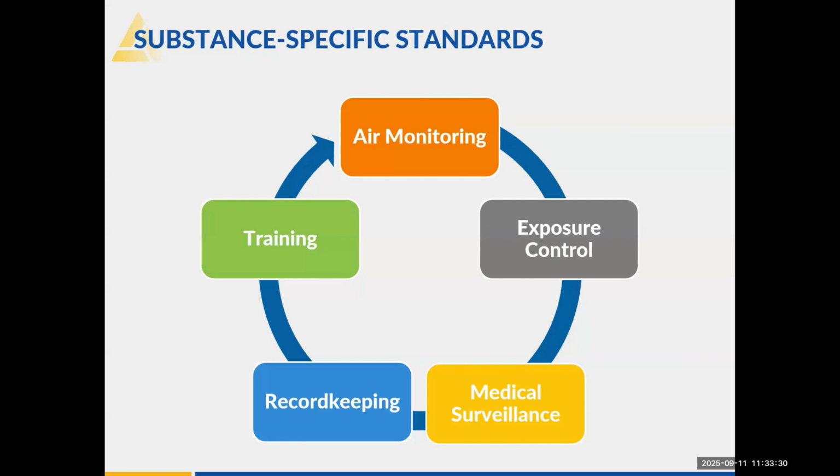This is something that is assessment worthy. Sometimes this is where you reach out to OECS to come in and help with that. But a couple of things that would clue you in are those signs that we talked about a little bit earlier. If you've got anything that hangs in the air, or an accumulation of any kind of substance on equipment, smells, or employees commenting on certain parts of their health, those are the first areas that you want to assess.